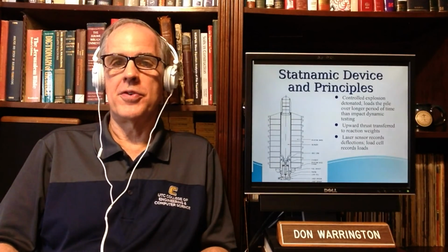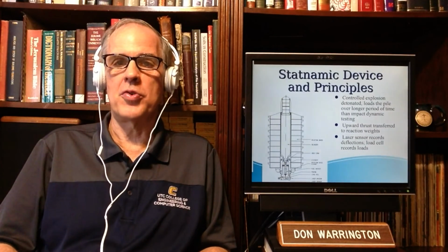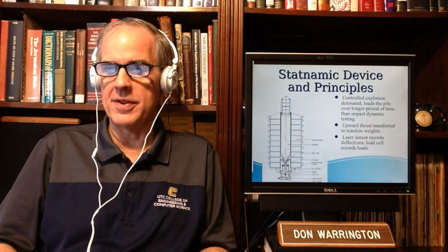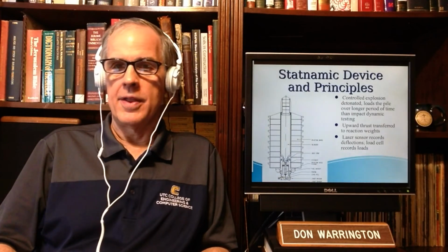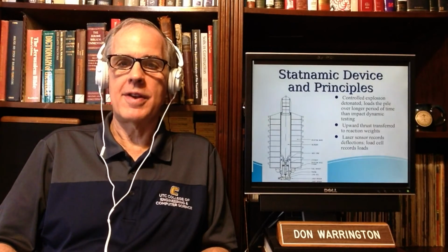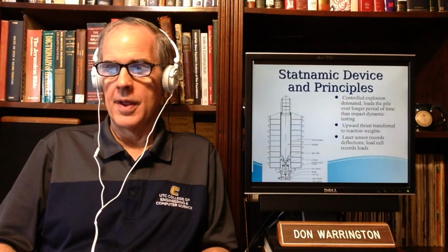And that is what Statnamic testing is all about. The basic principle of it is very simple. It has a controlled explosion. I know that Birmingham's people get very nervous when it's referred to as an explosion. Well, it's a controlled combustion. Let's just put it that way. It loads the pile for a longer time than the high strain dynamic testing we've been talking about.